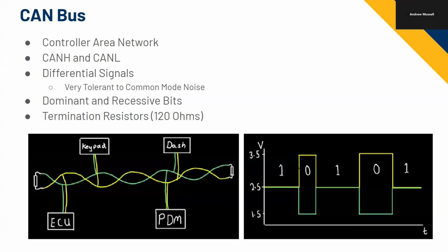Let's say it's 0 and I pull it high. It's kind of like when you take a rope and you whip it, that will propagate down. As it propagates down, every next bit of wire that it looks into, it'll be like, are you the same impedance as I am currently seeing? In this case, it's 120 ohms.